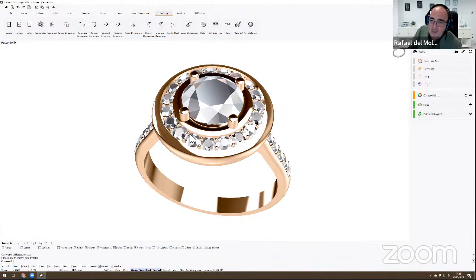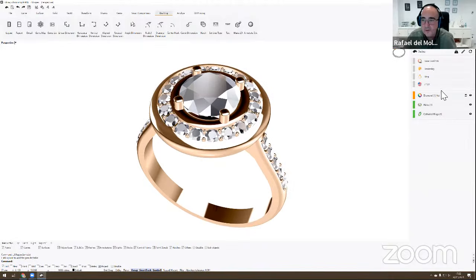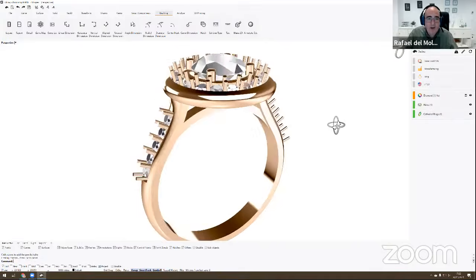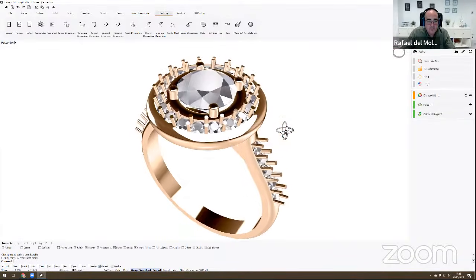Okay. Then imagine that you want to export that to production. You want to print in STL. We have a really nice property for the document, which is the mode. In the mode we can change anytime from rendering to manufacturing. Now we will change to manufacturing, and this change affects these 2 elements. Then now we refresh, and now we have the prongs longer for production.